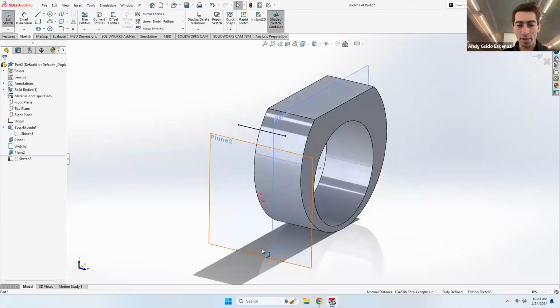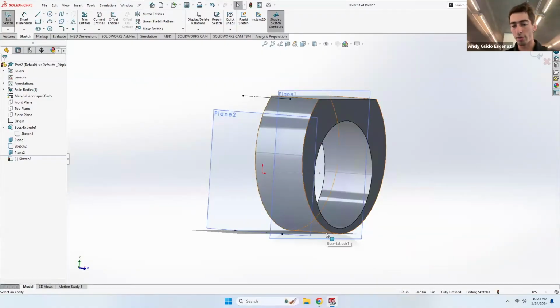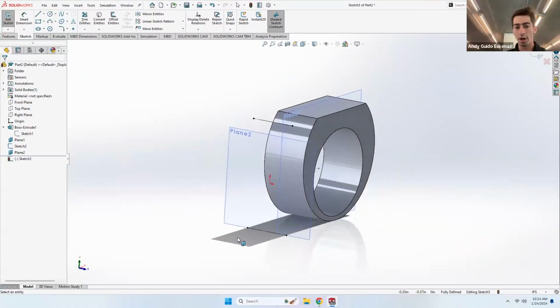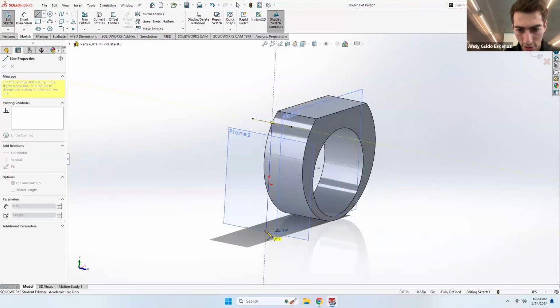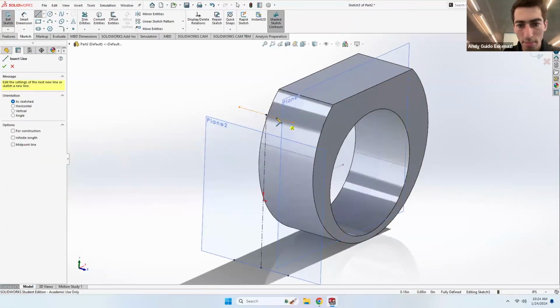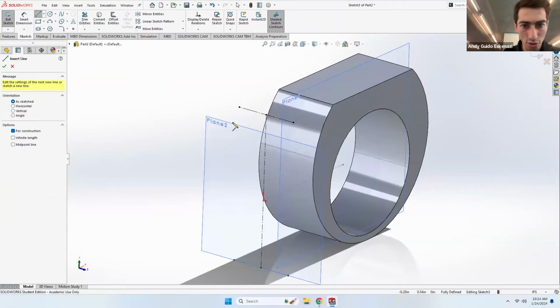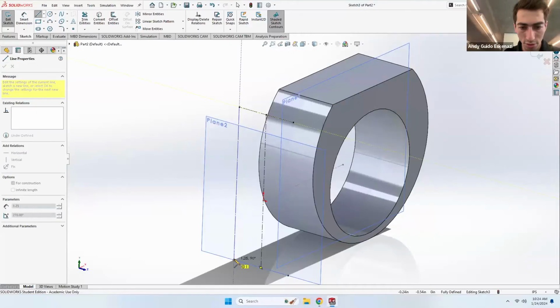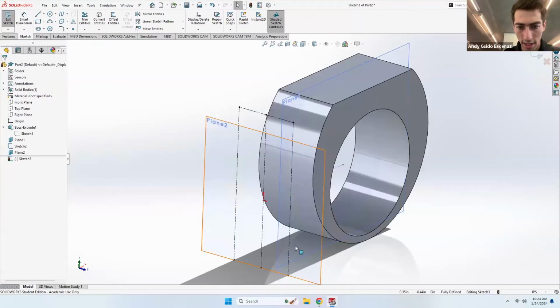So now you have those two, and I'm going to right click on those and make them construction geometries. In essence, I'm converting this edge, and the bottom of that silhouette, to this plane in here. And now that's going to be fantastic, because I'm going to do yet another center line that goes like that. And then I'm going to do a profile, and also two more center lines. One that goes like this, and then one that goes all the way like that.